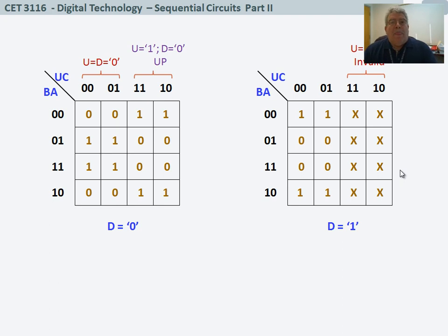Okay, that's how most counters work. All right. So we're going to be looking at something that perhaps is not easy to grasp. That's the first time that we're going to be working with 5 variable K-maps. What are our 5 variables? Well, we have C, B, and A, but also we're using either up or down. These are 2 extra variables that make 5 variables.